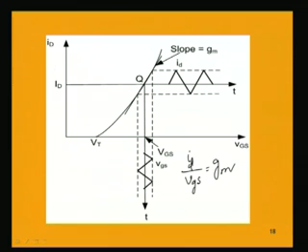So, the drain current versus the gate to source voltage curve, which is the transfer characteristic, starting from the threshold voltage. We should know more than one point to draw the transfer characteristic. So, from the current equation ID equal to K into (VGS minus VT) whole square, we can find out some points and join these points to get the transfer characteristic curve.